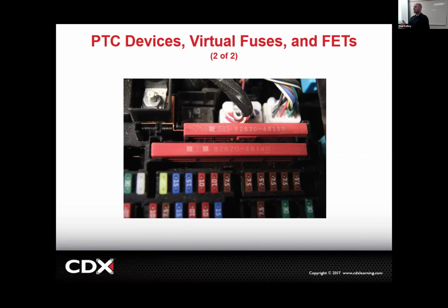So for example, back in the day, power steering worked on hydraulic fluid. And then they're like, no, that's not as efficient. It's kind of nastier. Let's do electronic power steering. Now you have at least one or two fuses in the fuse box that never used to be there. And it's the same with fuel pumps. Mechanical fuel pumps had no fuse. Electronic fuel pumps have a fuse. Now, back in the day, remember how you put the windows down like this, and you put them up like this, right?